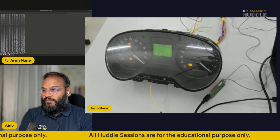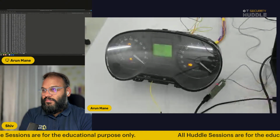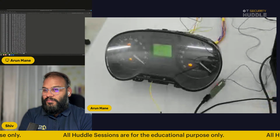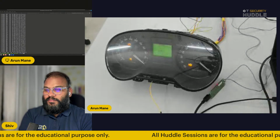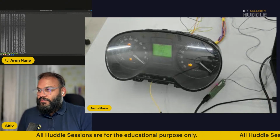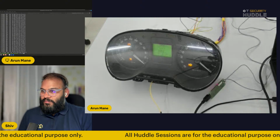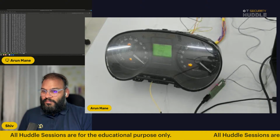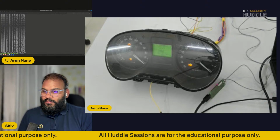In that case, we found a lot of vulnerabilities. It's a kind of fire hose attack you can perform. You will find the exact ID with exact data, which can be reverse engineered, and we can find the exact data as well. With the help of reverse engineering, you can perform these. These are nothing but a kind of CANBUS injection attack, followed by the sub attacks called fuzzing, virus attack.